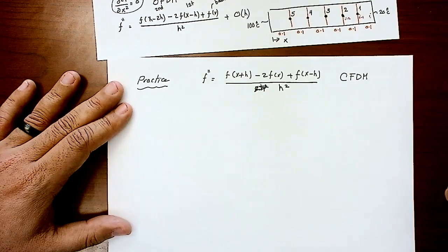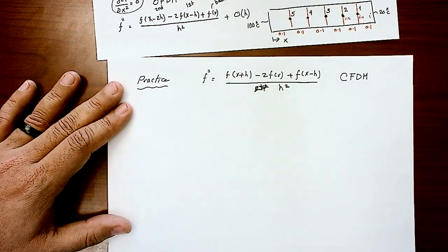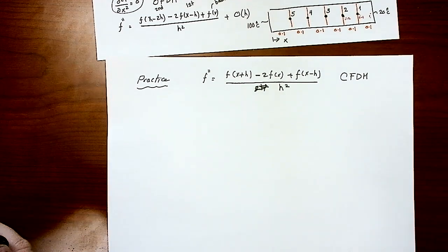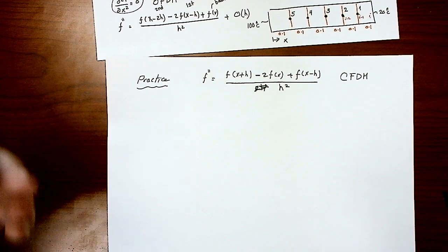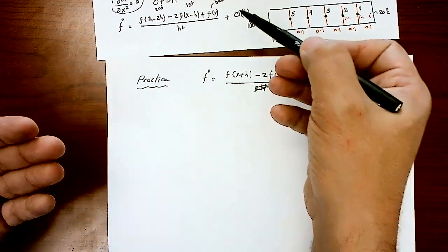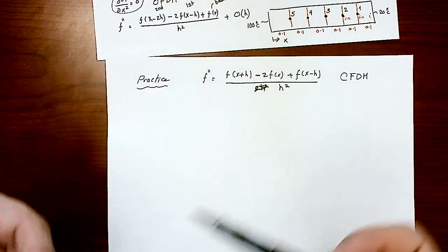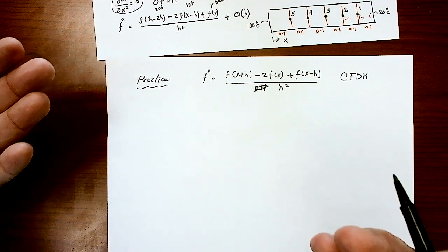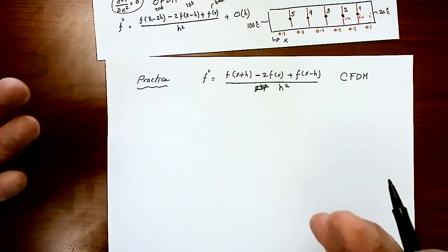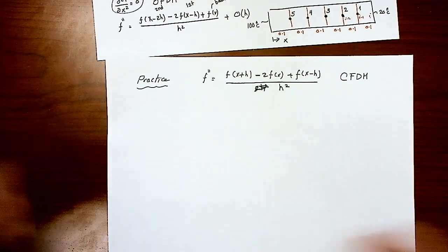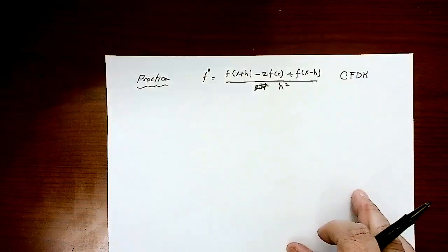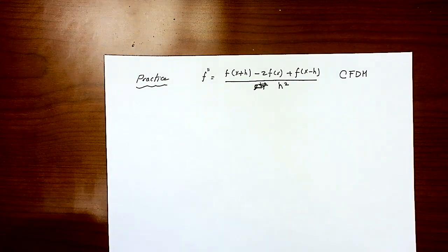Then you can compare what you got using the central finite difference method with the backward finite difference. Number 1, this is a proof that both are working fine. Number 2, you get a sensation of whether there is really a change in the final values, because we know the order of the error here is different from the order of error here. But maybe for this problem, you don't get a measurable error difference, but you need to practice that and look into it. And that concludes the one-dimension heat conduction example using the backward finite difference method.